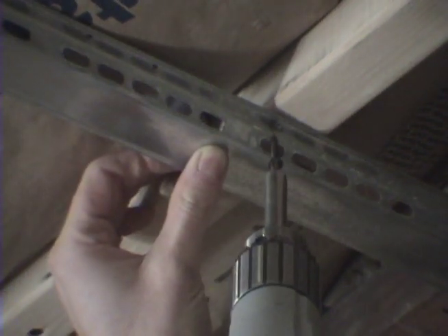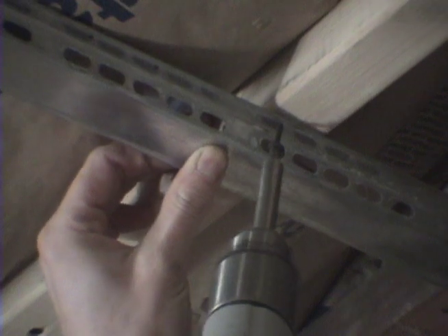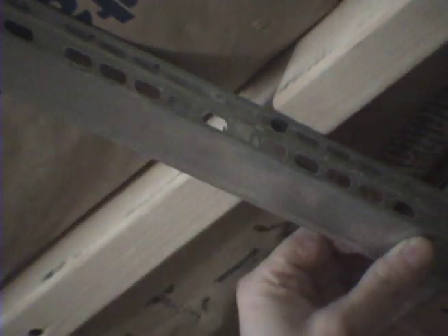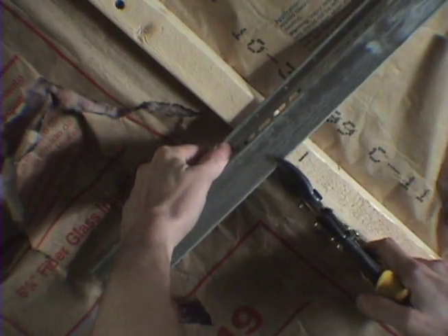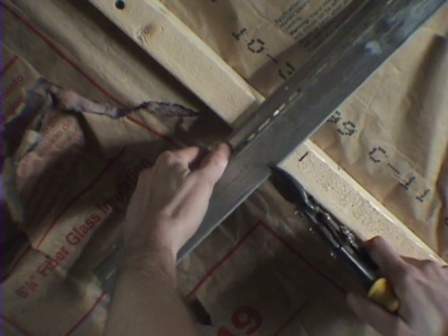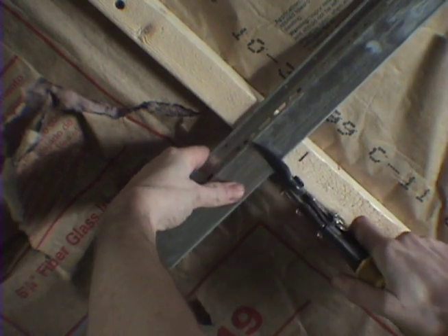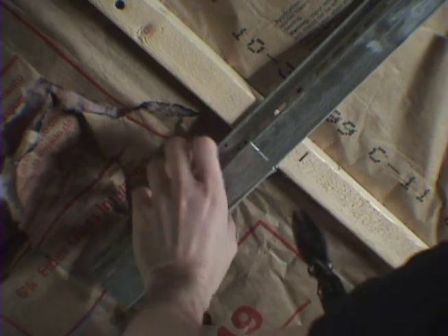These are attached perpendicular to the stud-work and are placed 2 feet apart. Place a screw through the RC and into the stud and you're done. Drywall panels are 8 feet long, so by placing the RC 2 feet apart, you will have proper support on the edges of each drywall piece.